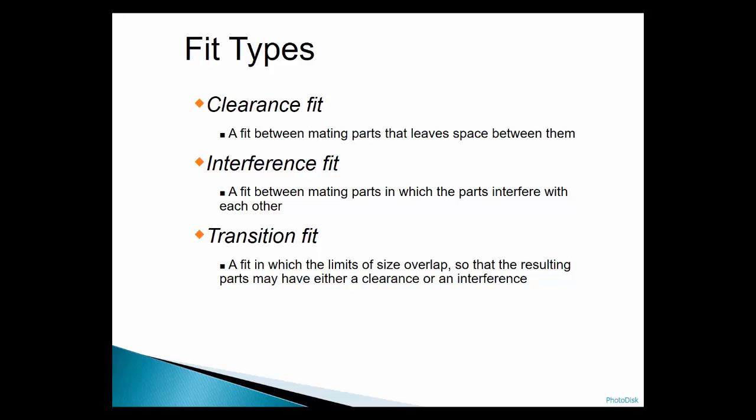There are only three types of fits between parts. Clearance fits means there will always be space or clearance between the two parts. Interference fit is the opposite. There is no space, but the two parts are interfering or overlapping one another.